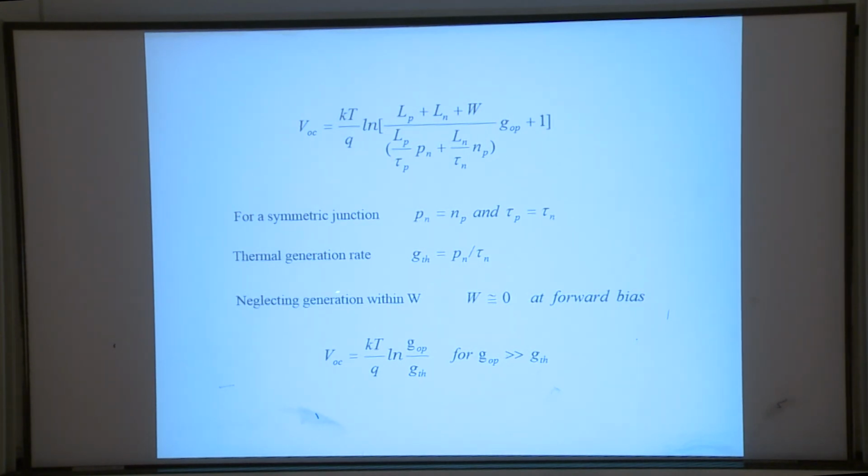All right. Then neglecting the width, because it's not under reverse bias. Actually, if you calculate the width, it is much shorter than the diffusion length. So under the condition of illumination, we can ignore the width without any problem, because usually the diffusion length for electrons and holes is much wider than the depletion region.